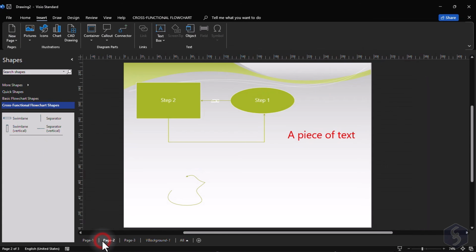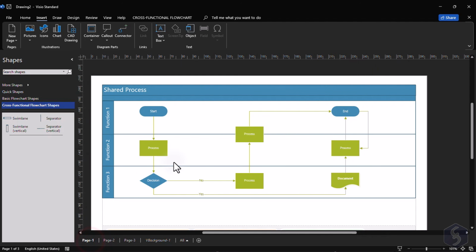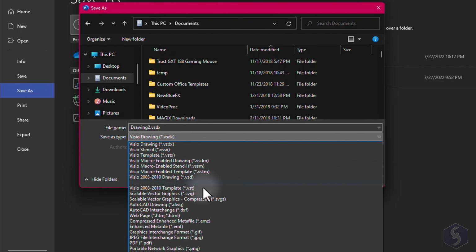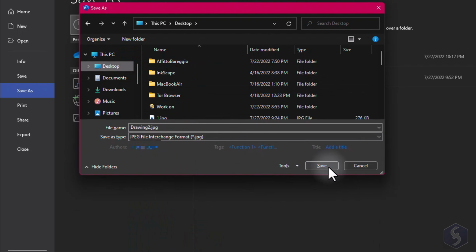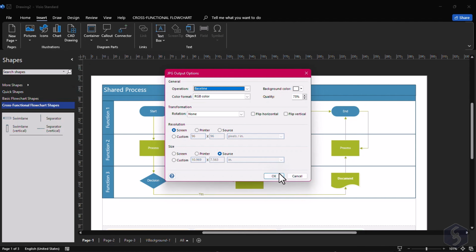To render and export the project, select the page you want to export and the right format, such as a vector SVG file for Inkscape, DWG to export to AutoCAD, or choose EMF, JPEG or PNG or PDF to render as an image or as a printable document.